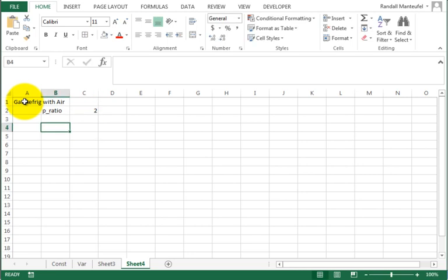Okay, so we're going to have a table of properties. Let's put state. Then we'll put our pressure at each state. Let's put our temperature in Kelvin for each state. Our enthalpy, which is critical. That's really what we want, in kilojoules per kilogram. And because we're going to use those air tables, we're going to use this PR. It's a no-name parameter. It's found only for isentropic processes in table A22. Because we're given the pressure ratio information, we would use that column in table A22.